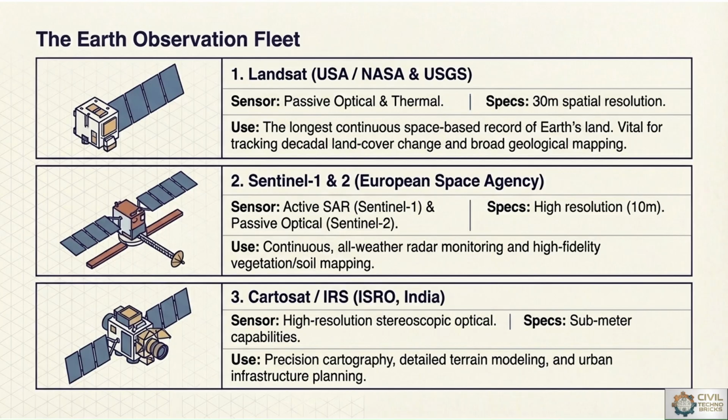Means these all satellite programs are launched by respective countries or agencies, for the sake of data collection or disaster management or any other application point of view. If we use that type of platforms for data collection, then we have to install some sensors, so that sensors collect the data effectively and efficiently with reference to its purity. Sensors for Landsat are passive optical thermal sensors with 30-meter spatial resolution.